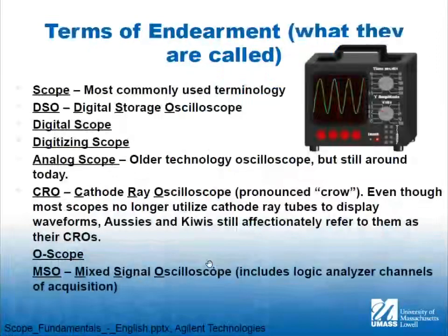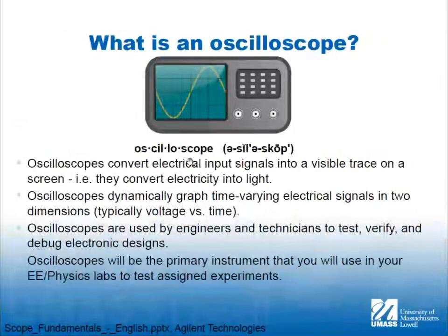So what's an oscilloscope, right? So is this circuit theory 101? Well, not really, but I wanted to define some terms. So of course it flips too. A time-based measurement is a case where we have a time-based generator, something that's going to sweep in time, and then we're going to synchronize the data that comes in to that time. And what it's going to do is give us a snapshot of a given piece of time. And that's exactly what oscilloscopes do.